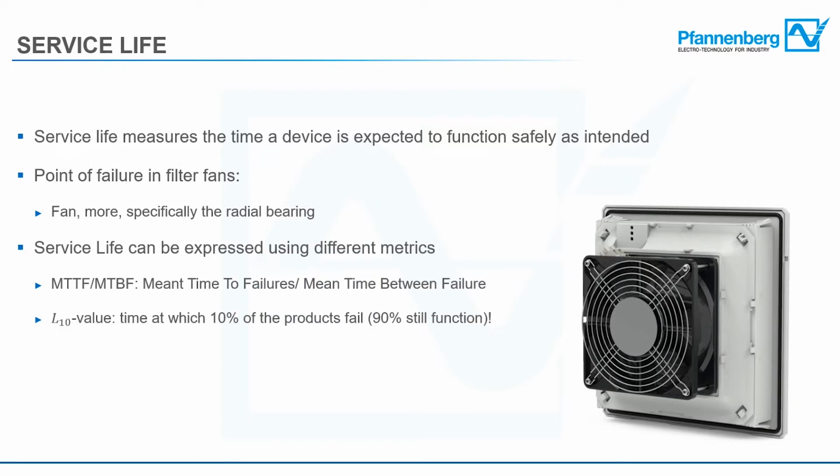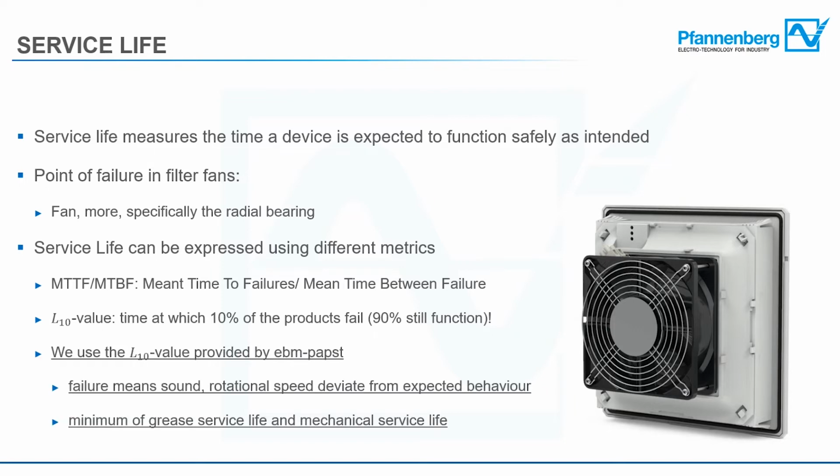Service life can be expressed using different metrics. A couple of them are the MTTF value, which is the mean time to failures, or the MTBF value, the mean time between failures. Another one is the L10 value, which you might already be familiar with, which is the time at which 10% of the products fail. Of course, what this also means is that at this time, 90% of the fans still function.